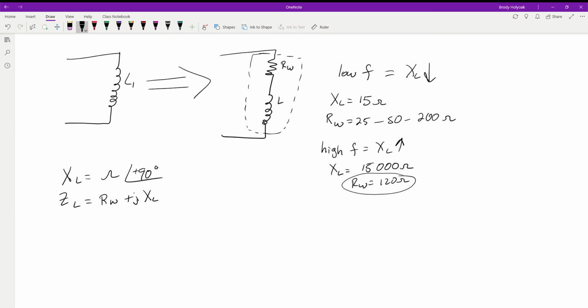So each one of these inductors is going to have a rectangular impedance value just for the inductor itself. So we're adding on a little bit more than what the capacitor was. Because remember, when we have our X of C, let's say it equals some ohms at negative 90, when we write down its impedance, it was equal to 0 minus J of whatever that value is.